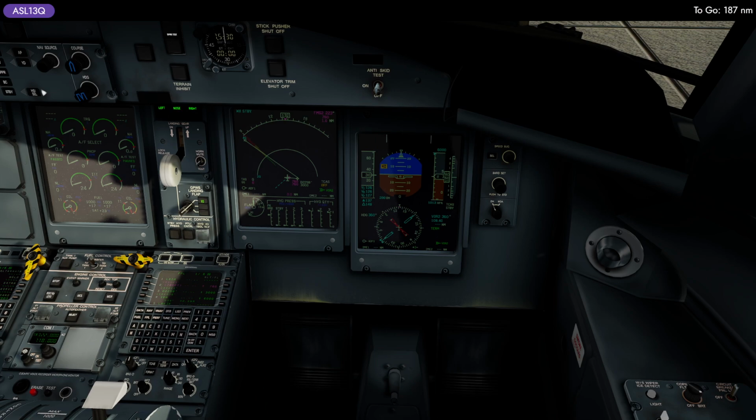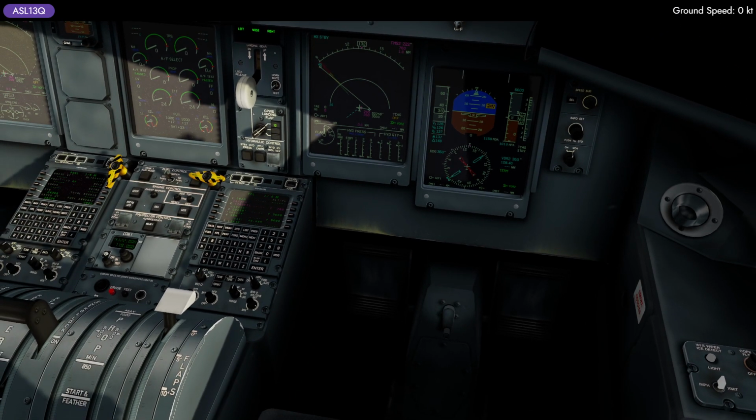And I like to use DH for that, so 1000, or since we are using the DH, let's just go with the 800 feet above ground level. No, it's my bad. We are using the DH, we are depending on the radio altimeter, which can be different, so let's just set the MDA to 1150.